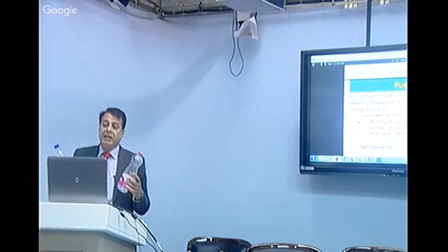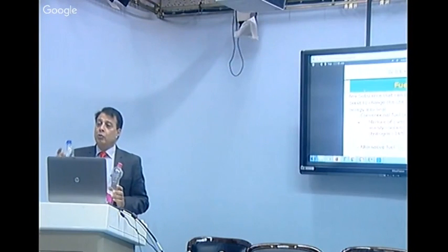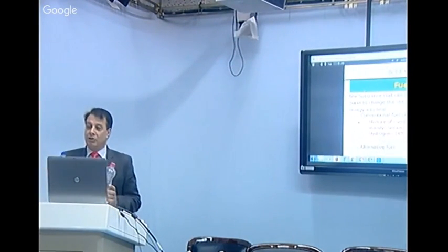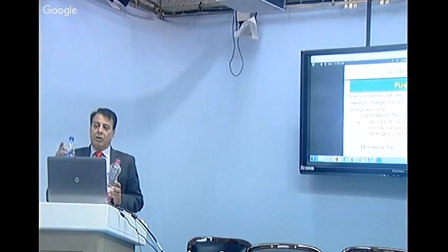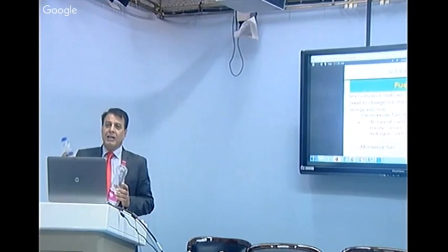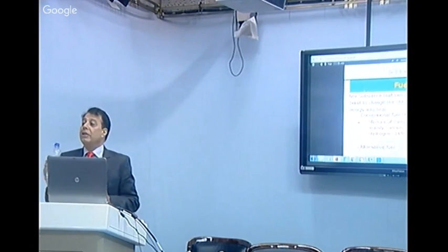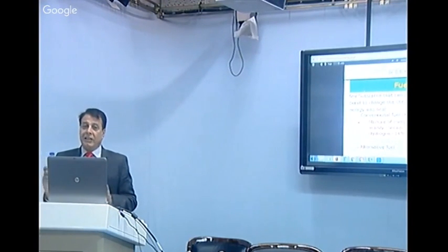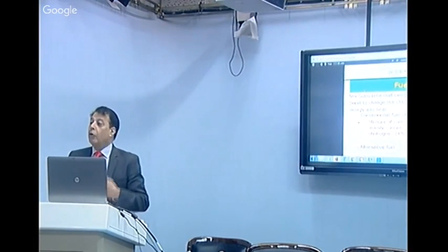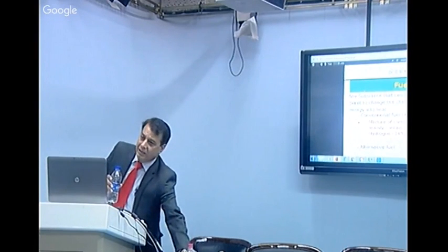Similarly, I am designing an air cleaner for use in the vehicle. What should be the dust holding capacity? You can note down this terminology. Like this bottle can hold 200 ml of water, similarly all air cleaners are designed with a dust holding capacity. Whether they can hold 10 gram of dust, 20 gram of dust, 40 gram of dust, you can decide at the design stage.